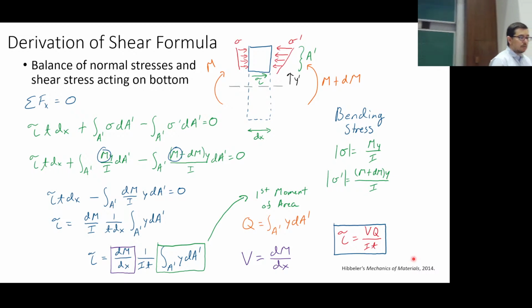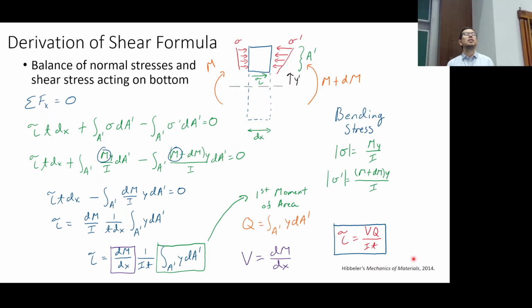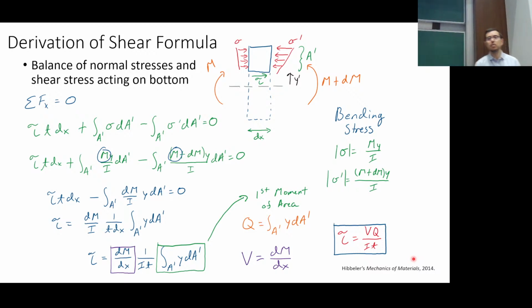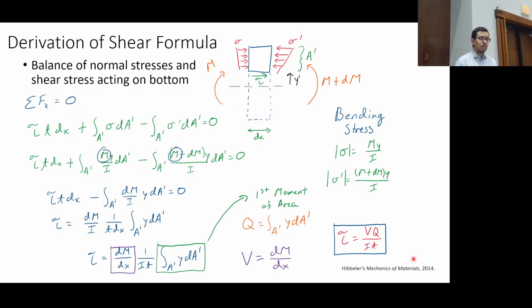And this equation, we'll talk about how to go about solving problems with it, but it is significantly more difficult than what you have with bending stresses. In reality, I'll show you some shortcuts that you can use for most cases, so it becomes not that bad of a problem. In most exams, I have not really asked people to do a detailed VQ over IT, but they use some pre-derived expressions for maximum transverse shear stress.